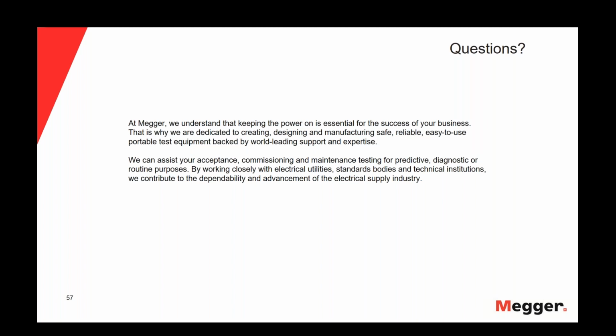The IEC standards, so this is how it works. IEC itself does not have a dedicated VLF standard. It has all kinds of apparatus standards and test practices standards, and there's one for high voltage testing. And this standard, the 660, also contains cable testing after laying installation, everything, and it will refer you to a regional standard, which in this case is Cenelec. And Cenelec has 2 parts that are relevant for this, HD 620 and 621.